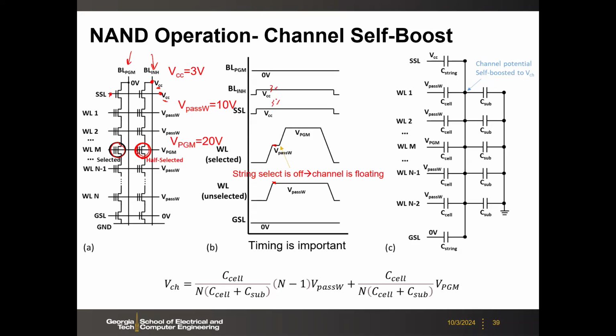And then, the reason for this 3 volts, because here you have 10 volts, so this transistor actually is off. This transistor is off, because here the VGS is 0, right? You have the gate at VCC, and on the other side this is a higher voltage. So this becomes a drain, this becomes a source. So this is like VGS.